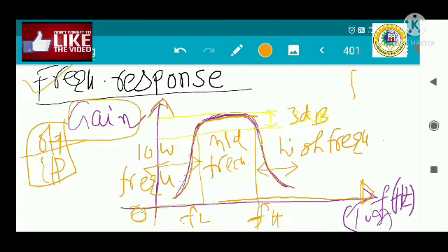Till now we have not bothered about the source frequency. We have not mentioned the frequency of the input source, and we have calculated the gain assuming that the gain is fixed throughout the range of frequency, whatever the input signal frequency may be. But that is not the case. From the diagram you will easily see that if we change the input signal frequency, the amplifier gain will change drastically.